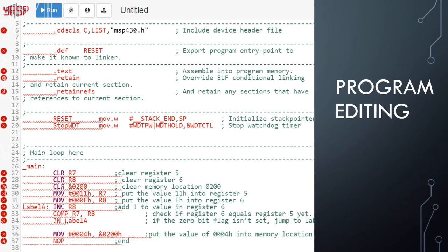So we see up here on line 6, we can't hover over the X in this mode, but this is probably extra and we don't need it. So we can probably delete a lot of this stuff in the top. Some of this stuff, you might notice that the register numbers are a little bit different. We usually use B as a register number. This code is using memory locations, which we don't have access to in this particular compiler.